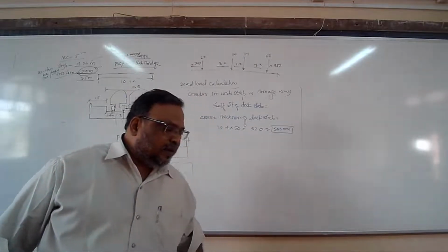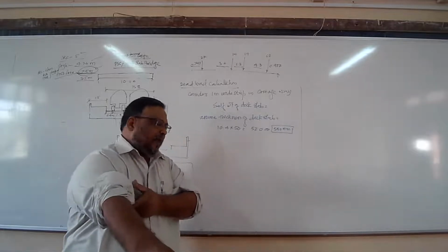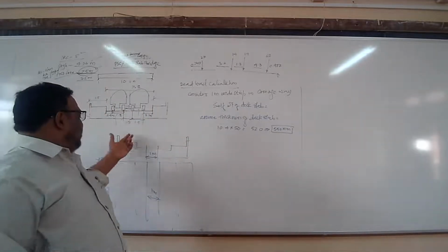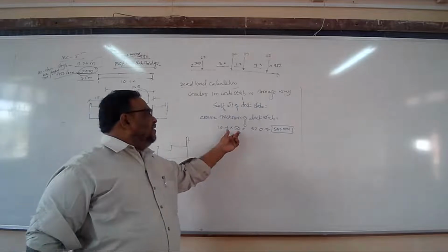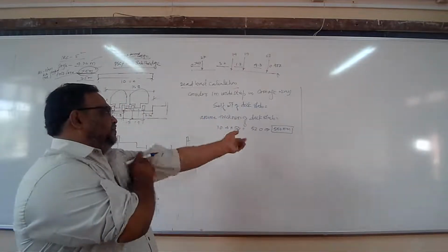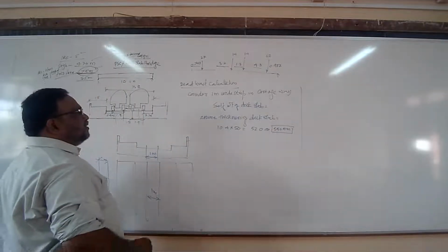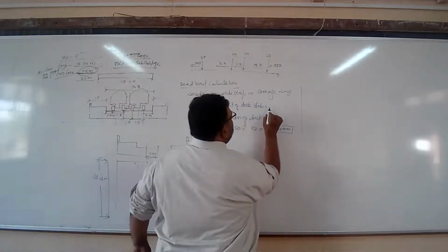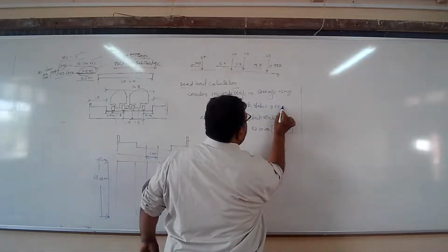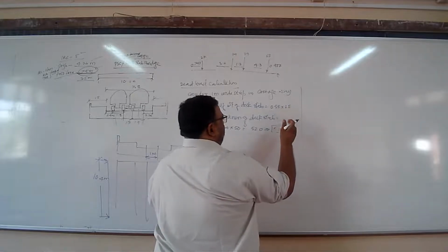Okay, you are right, Amir. You are right. 50 mm per meter span. You are right. Span is 10.4 meter. Say it is a thumb rule. We are assuming, finally we have to check. 520 came. On the higher side we will approximate 550. Then what must be the self weight of deck slab? 0.55 multiplied by the unit weight of concrete, which is 25 kilonewton per meter cube.